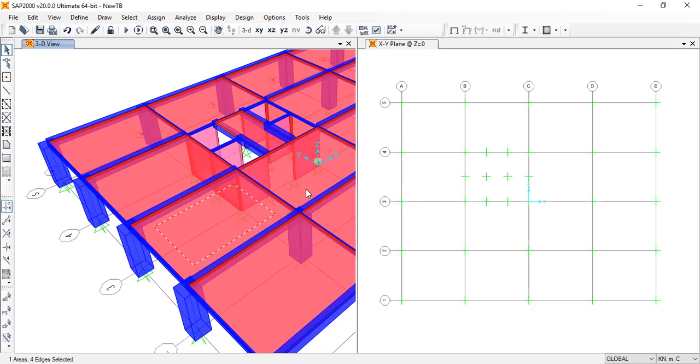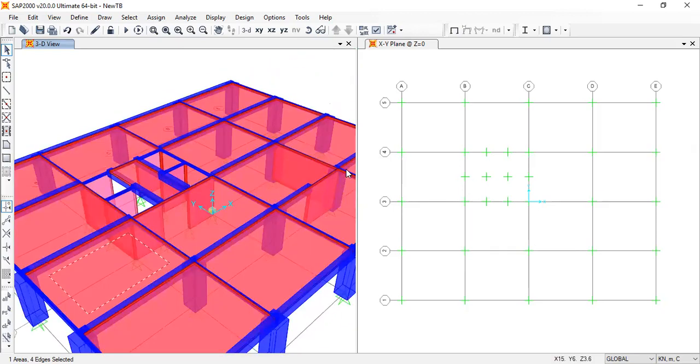So the problem is if you mesh all of these panels, let's say at around 0.25 to 0.3 intervals, okay? That is a fairly good mesh, right? You use small 0.3 by 0.3 squares to mesh it, and imagine you will have many small elements within the slab, and when you multiply with the number of stories, you will have a large number of meshed elements, right? So your computational time will be much larger. If you have a good computer, that's okay, but that's not needed for that, right?